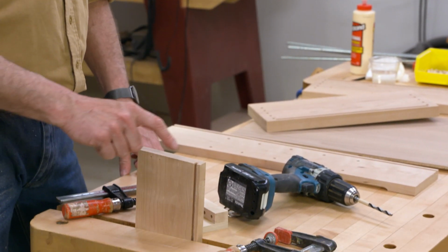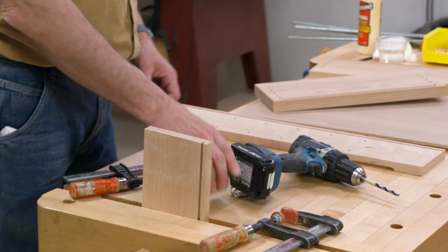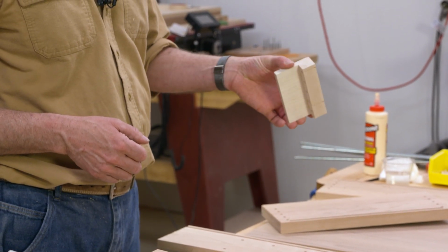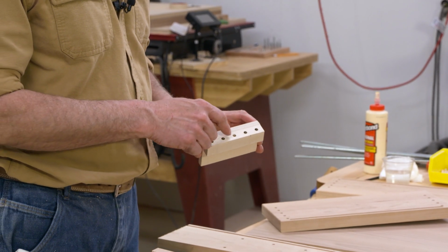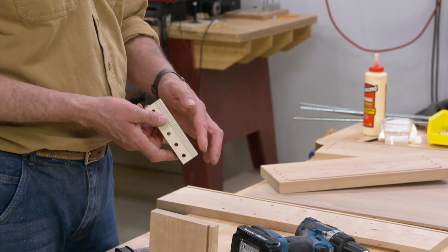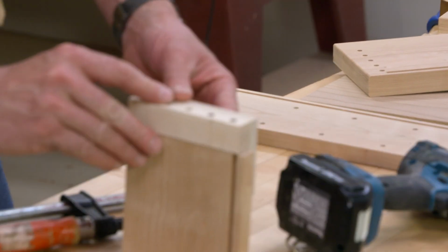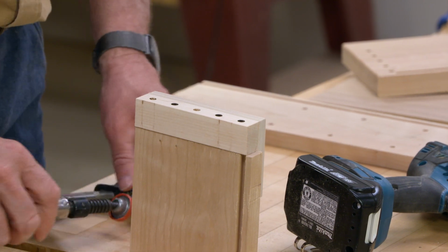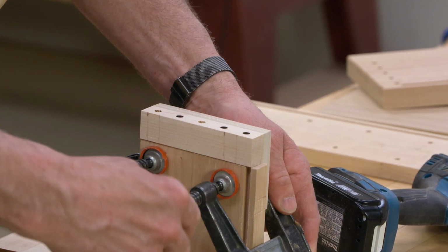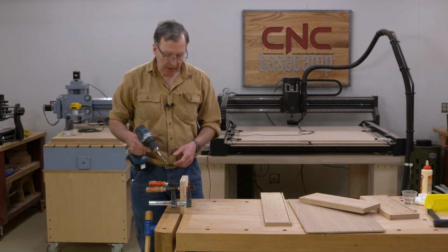The one thing the machine can't do is drill the holes in the end of my sides, but it can sure help out. What I've done here is just make a simple CNC shop-made doweling jig. The machine drilled 5 holes which perfectly match the spacing on my top here, and I simply glued a little piece of wood on as a reference so that I can clamp it to the outside face of my side. I simply line it up with the front edge of my side, clamp it in place. I've got a drill bit flagged to the right depth, and I'm ready to go.